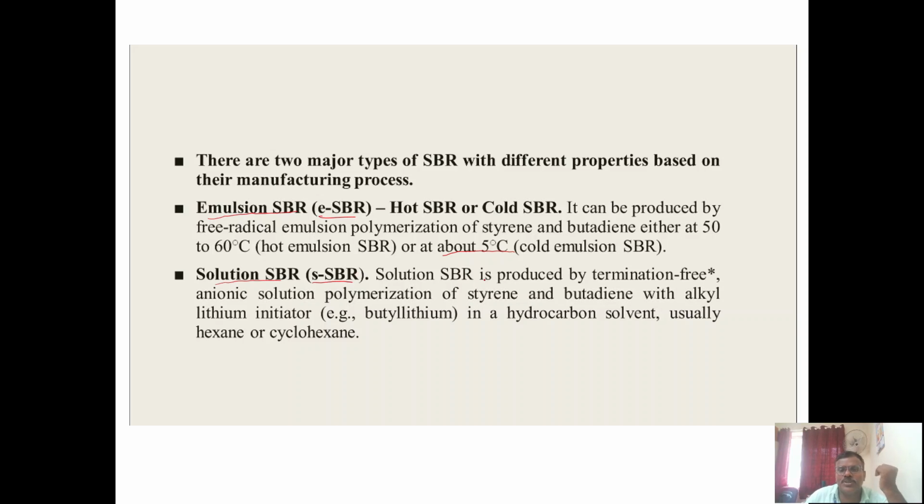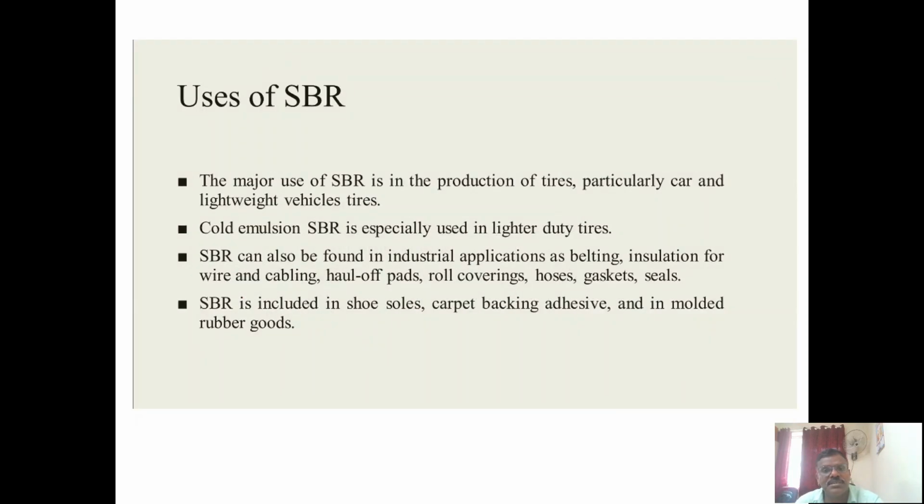Solution SBR is produced by termination-free anionic solution polymerization of styrene and butadiene with an alkyl lithium initiator, that is the catalyst. And what is the solvent? Hexane or cyclohexane. It is a solution polymerization reaction.